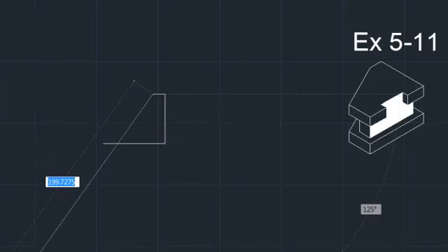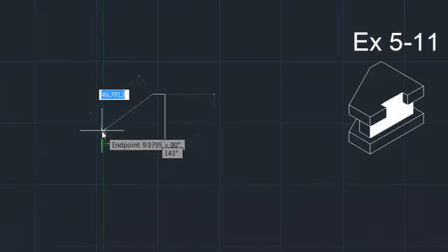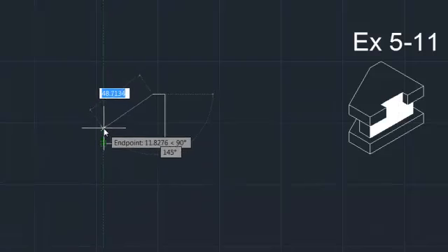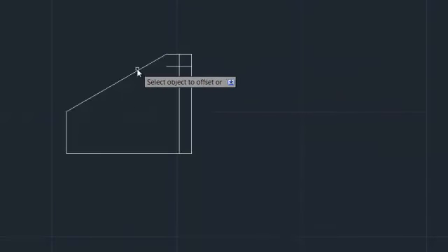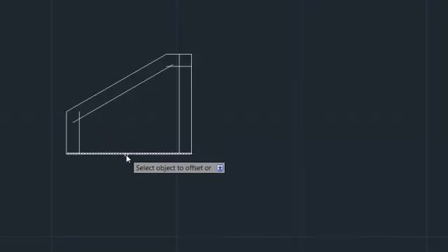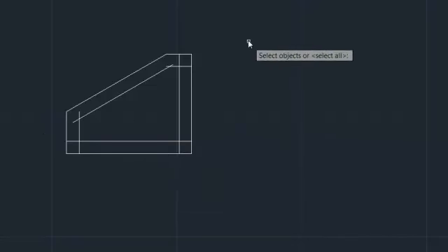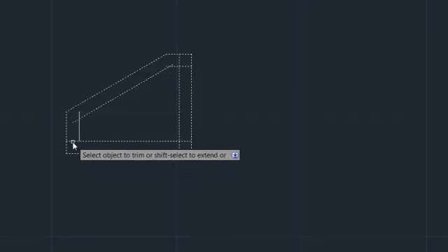I've already set my object snapping, polar tracking to lock in at 30 degrees. So I can mouse up from that corner, get my extension tracking in, and bang, that's where that line goes. Now you'll notice as well in that drawing it says 5 all around is the dimension from the top and bottom face to the inner face. So I'm going to offset all of these lines a distance of 5. This is going to form my hidden lines. It's also going to help me define the position of the points underneath when I come back around there to draw the other views.